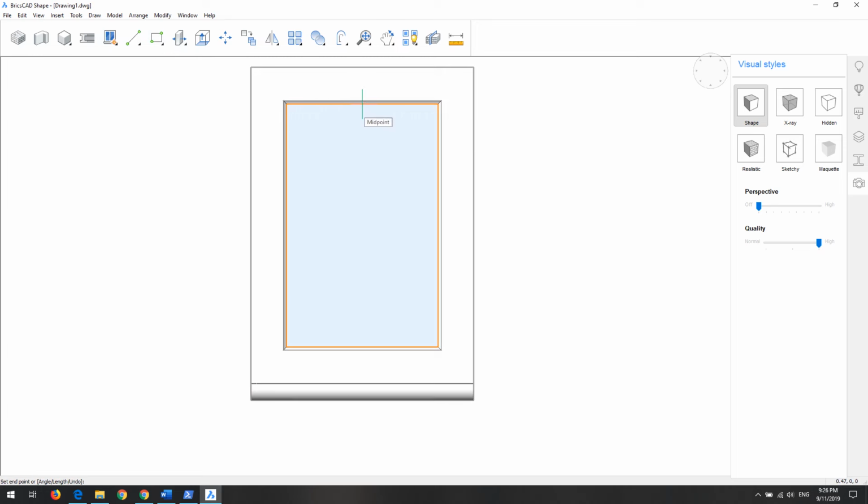And here draw the center line. So we are dividing this section into two equal parts, but again use the null line to get a snap from here to here. Now we divided the region. Suppose we want to move from the center. We want to create a move from the center 0.2. So here we created 0.2.